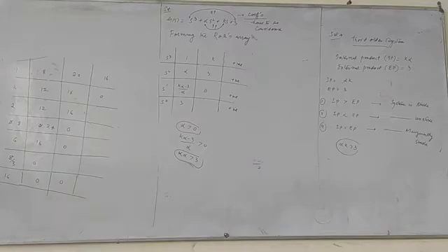The number of open loop poles in the RH right half plane. The number of open loop poles of right half plane, RHS plane is also called, there is no difference in this. Poles of G of S is given. So he has given open loop poles. So you have to find number of poles for this only. No characteristic equation 1 plus G of S, that has not to be done. Whatever has been asked, you have to find for that.